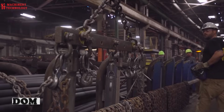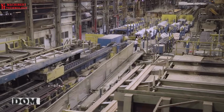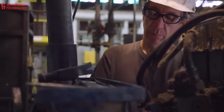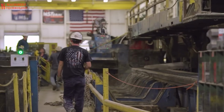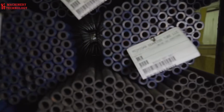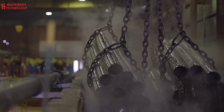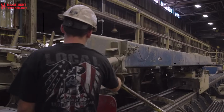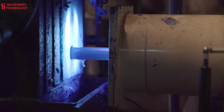DOM production process. Drawn over Mandrel. DOM, round mechanical tubing, is a cold-drawn 1020 or 1026 electric resistance welded tube with all the flash removed prior to cold drawing. In comparison to other tubing, DOM round steel tubing is produced to more exact OD and ID tolerances and has the highest weld strength possible.